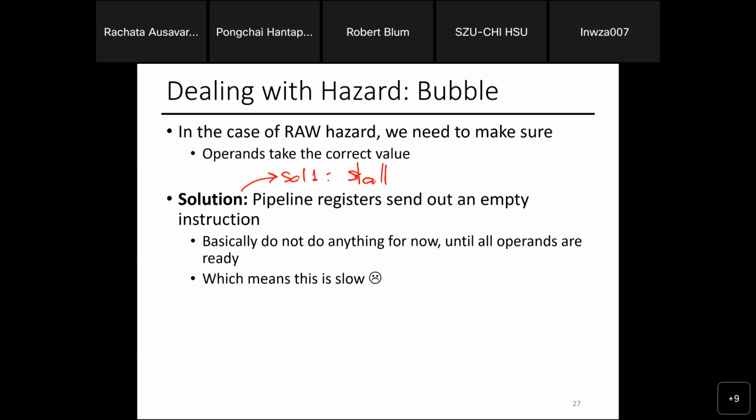And you might be surprised how many bugs can happen with the other technique. This is simpler, right? From the let's-design-a-chip-for-the-first-time point of view, this will be like your checkpoint 1 for the pipelining lab. Well, checkpoint 2, checkpoint 1 is let's make sure you can pipeline. Checkpoint 2 is make sure you can stall correctly. Checkpoint 3 is do the data forwarding, solution 2. Right now, what we do is, if we detect data dependency, stall until the data is updated, then I move forward. Right? It's simple. Also, downside, slow.